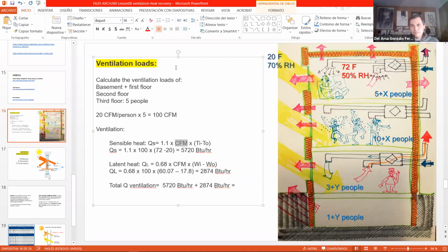But in commercial buildings, in buildings in which the occupancy is above, I don't know, 500 people, this is mandatory. So now we have to use heat recovery systems in large buildings, because all building codes have made it mandatory, because there were a lot of energy losses or ventilation loads, especially in large buildings. So we need heat recoveries.